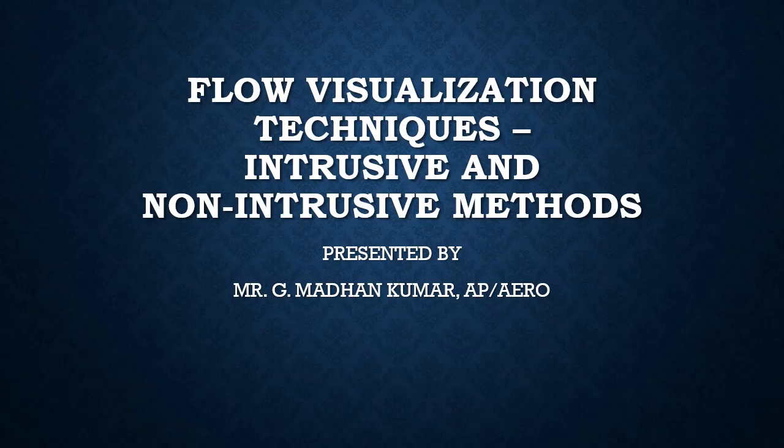In today's session, we are going to discuss flow visualization techniques, intrusive and non-intrusive methods. You know very well about intrusive conditions. What is meant by intrusive? If you are doing any disturbances to the flow, that is, we are going to visualize the flow by creating some disturbances, that is called intrusive. That is, we are going to change the field of the flow.